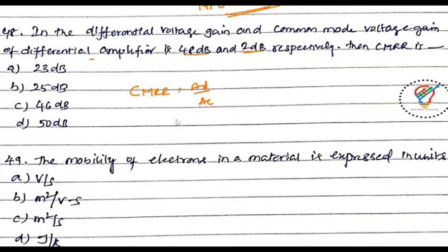In the case of dB it is 20 log, but all the given values are already in log, so directly AD in dB minus AC in dB. That's 48 minus 2, which is 46 dB. Since the given data is in dB, we subtract directly. So the answer is 46 dB.